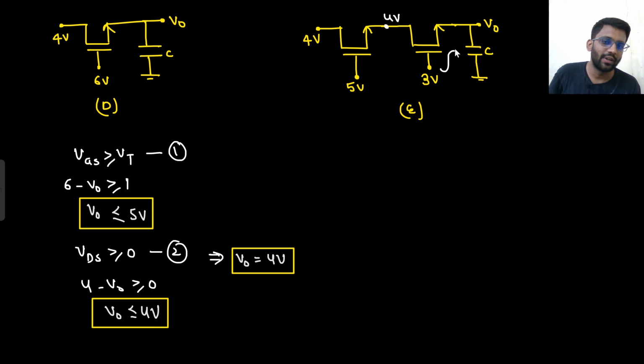Now again from here to here, what will be the final voltage? 2 volt. So you can say 2 volt. But after that you will see at the drain as well. Can drain apply me 2 volt? Yeah, drain can supply you 2 volt. So your steady state voltage at the source would be 2 volt only. Did you understand this question? You started from here. This is 5. You can go up to 4 volt and drain can also apply 4 volt.